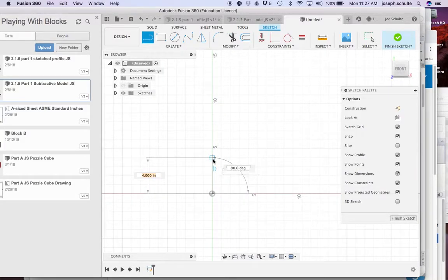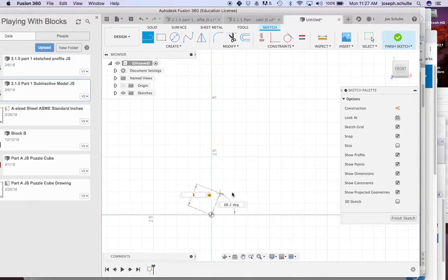That up number was 1. Zoom in some more, and then I'm going to keep drawing, and when I get that 1, I want it to snap vertical, click, and now I'm going to, without doing anything else, go over, and that should be 1 as well. It already snaps to that, and it gives me some other constraints that are called geometric constraints. We'll learn about those more later. That would be a 1.